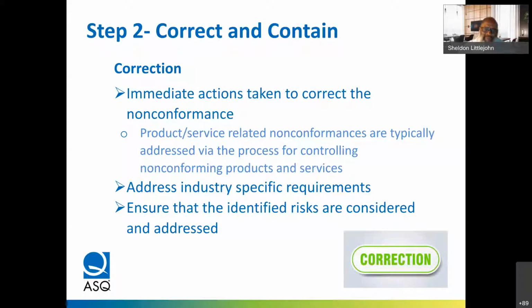One of the things that I think could be mentioned at this point as well, in designing your quality management system, it's important that you consider these corrections and the steps to ensure that you're able to execute on these actions. One thing that comes to mind is calibration, in regards to control of your calibrated equipment. We may lose traceability of what products are measured using specific gauges.